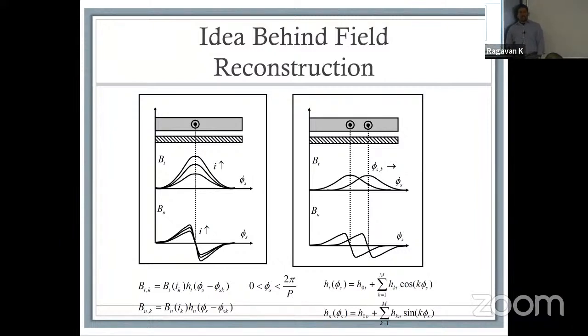Basis functions are like a unitary function. If you remember, when we did superposition, if you are trying to do it for 5 volts, we would calculate the unitary function for 1 volt, and then whatever the voltage is, we just multiply it by that. That's the same idea. We don't care about what the field is, because if we have one distribution for one geometry, we know what that's going to look like. Now we can recreate it for the same geometry with any current.